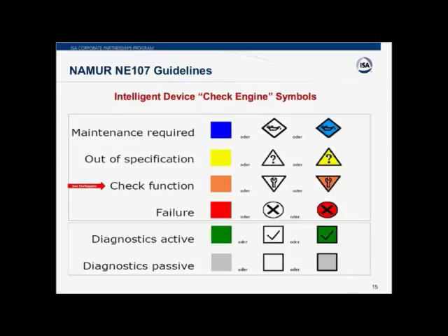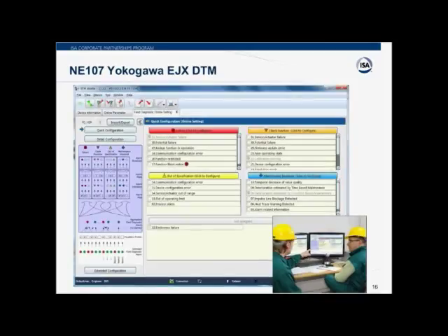So with that bit of background of just what is possible with the FDT technology, we have another example here. Again, this time we're using a Foundation Fieldbus device, and you can see we've got the 4 categories, and here you see that we have a mismatch on the function block, which is causing a failure of the device to effectively communicate with the host. But look at the granularity that you can obtain through the intelligence of your device.